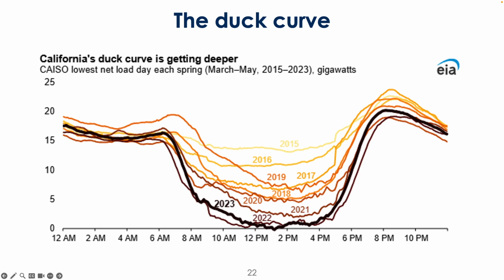And a lot of folks have attributed that increase in storage to solving a number of issues, including some of the peak power stuff that had happened in like 21, 22. We haven't had to do that since, and a lot of people say that's because of the additional storage capacity that's been installed. And certainly that's going to help with some of this stuff as well, both to soak in the curtailment when you want to reduce the ramps, but also to just generally help provide extra fast ramping resources during these times.